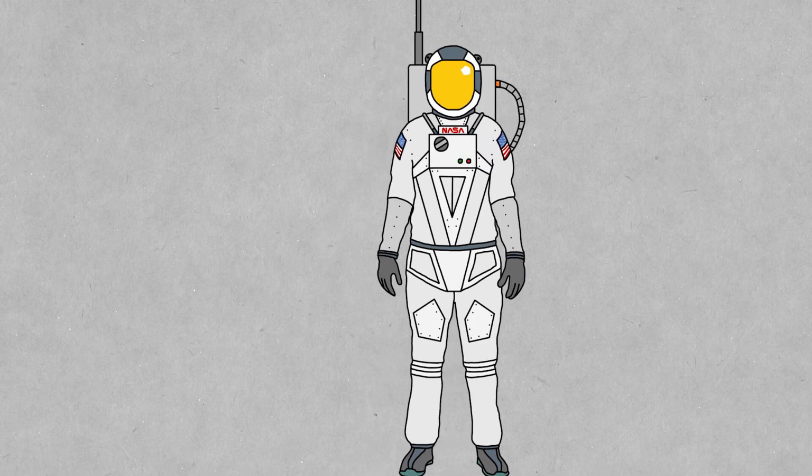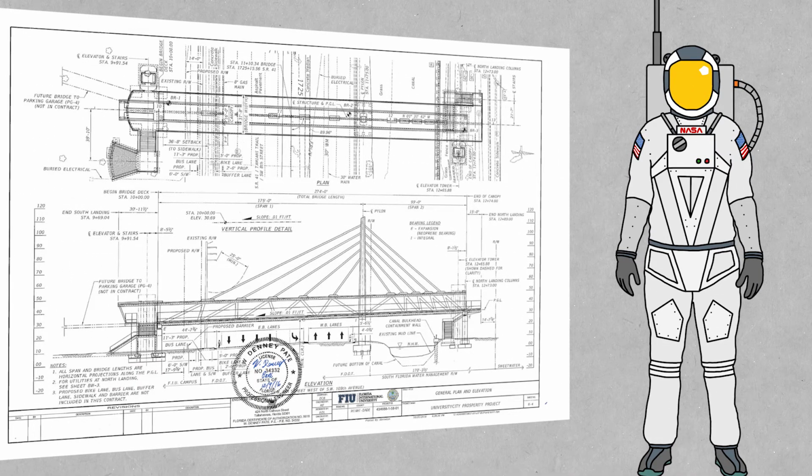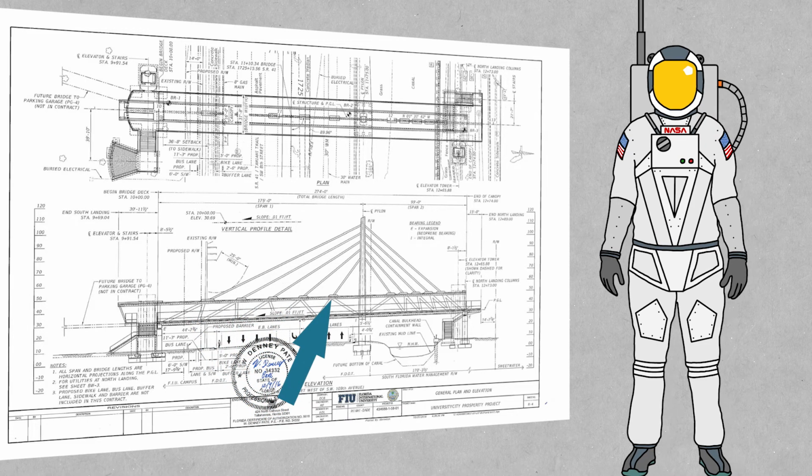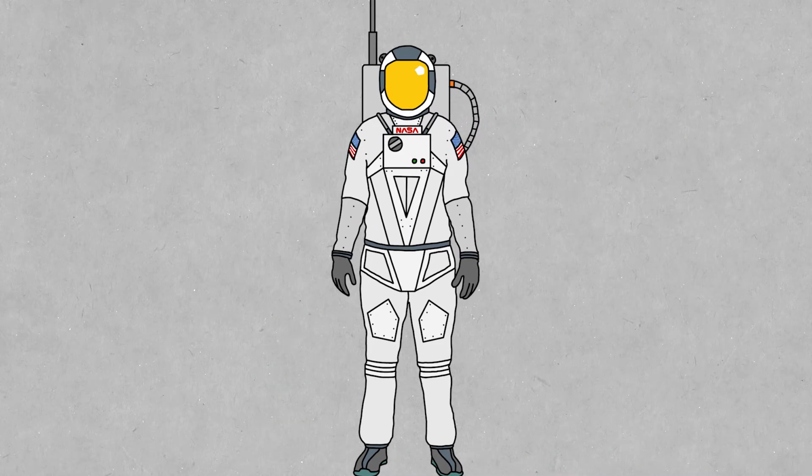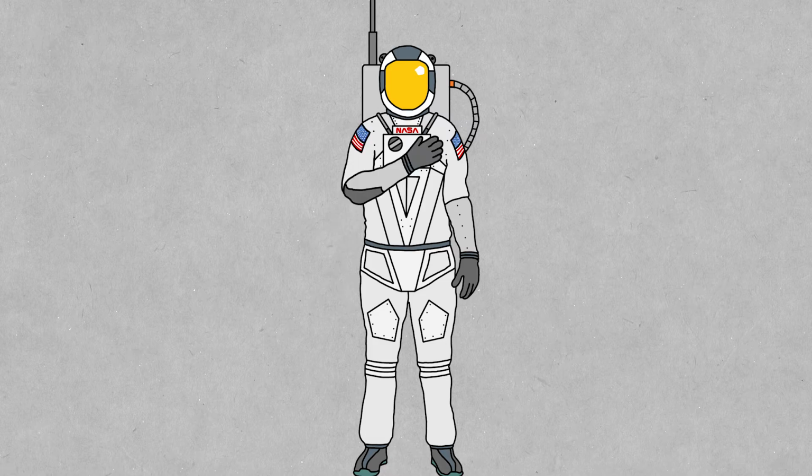I did work with my brother to create a model of the bridge, and we analyzed the stress on it. This revealed that there was one member which was under a lot of stress, but after doing some more research, we found that this area had actually been reinforced, and it wasn't even the place where the bridge broke. So our surface level design analysis indicates that the bridge was probably properly designed and the failure might have come from somewhere else. I won't say anything more than that because it would just be speculation, but I will try to make a video when the official report is released.